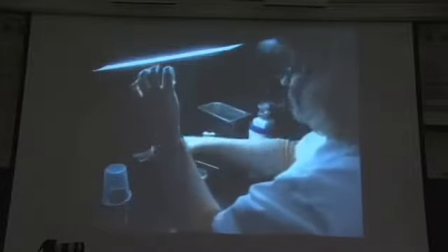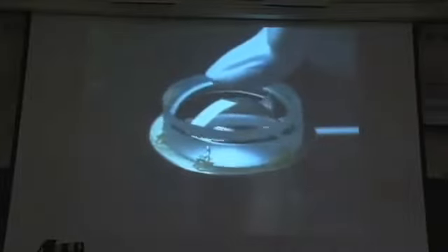She gives the other concave lens a little more scrutiny before she cements it onto the convex lens. She applies pressure to spread the cement between the two lenses. Cementing them together means they'll be less likely to shift around in the lens barrel.